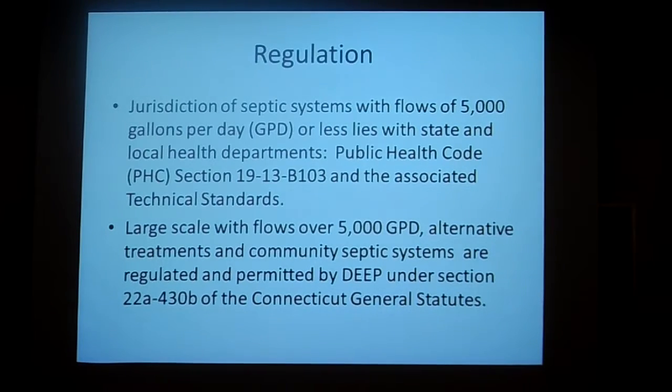They are regulated by two different agencies. A septic system with flows of 5,000 gallons per day or less lies at the state and local health departments. These are regulated under the Public Health Code, section 19-13-B103, and they have associated technical standards.